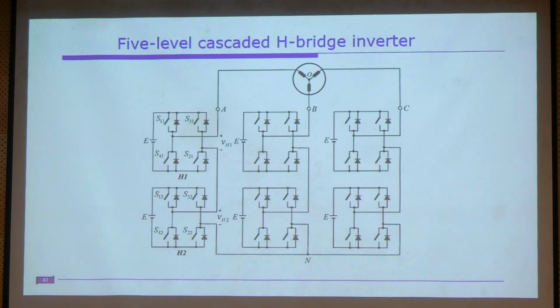So the next one, which is commonly used nowadays in the electric vehicle drivetrain, is the cascade H-bridge inverter, right? This is especially used for high power motors, maybe exceeding 1 megawatt, 2 megawatt electric drives, which is a very high range. So this kind of converter is preferred.